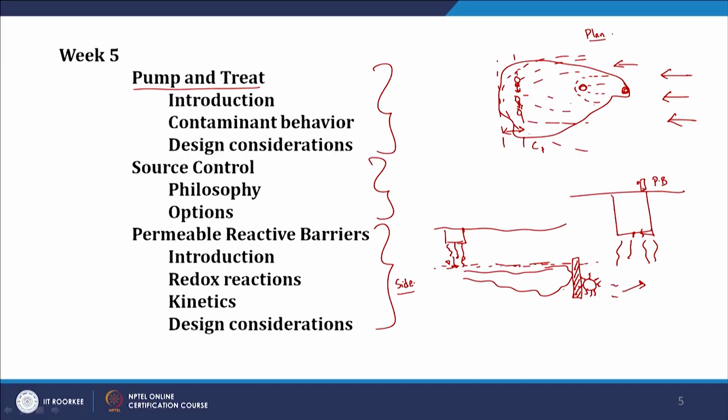I am going to build a permeable reactive barrier. It is going to be relatively porous, because you would want the contaminated plume to flow through the barrier and not around it. For example, if the hydraulic conductivity of the barrier is less than that of the surrounding aquifer, the plume would want to flow around it rather than through the barrier. Again, path of least resistance.